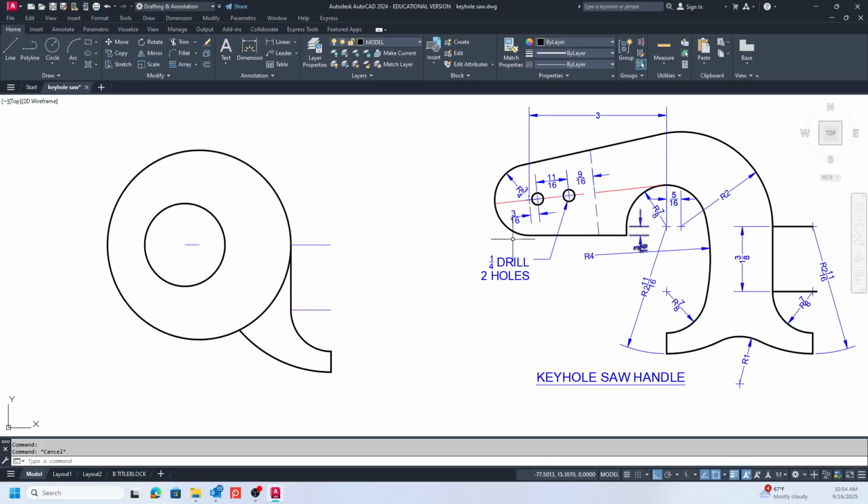This leg comes off of our reference line left-hand side, and we're going to put a straight line down from right here, 1 3/8 down, to give us this reference mark.